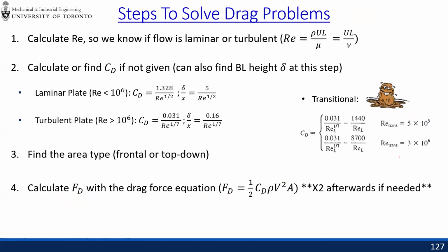Now, there's a four-step guide to basically solving drag problems, 4 or 4.5. So first of all, Reynolds number, because again, our drag coefficient is a function of Reynolds number. So you're going to need your Reynolds number to actually find the drag coefficient quite often.